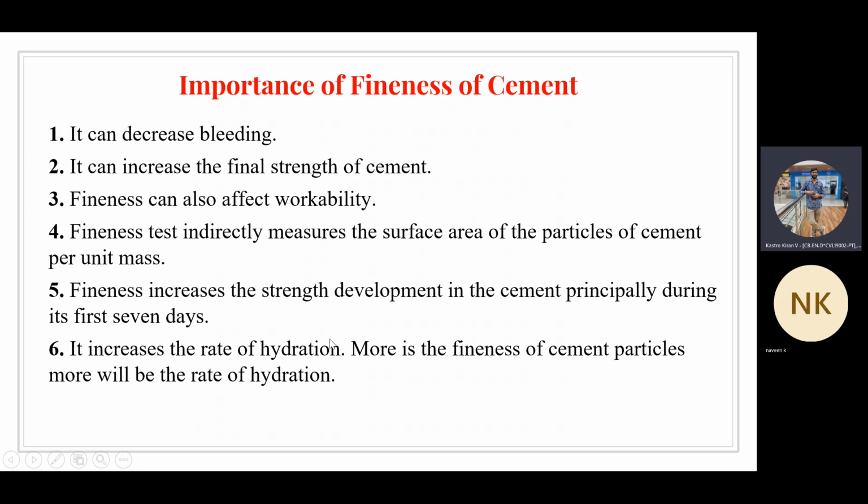Because of these reasons, we are going to do the fineness test of the cement. Whatever cement you get at the site, you have to send that cement sample to the laboratory, and the results should get validated. So that's about fineness of cement.